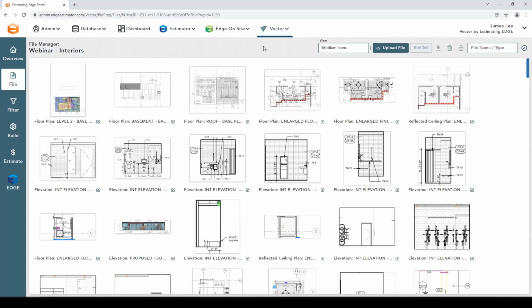So what you're seeing here is a list of all the sheets that the architect has made available to us inside of this Revit file, okay? So these are so much more than just background images. These are the plans that you're accustomed to working with every day, floor plans, ceiling plans, sections, elevations, and details. But besides just the image of the plan, they're also going to contain actual data from the model. The three-dimensional model is going to be broken up into these different sheets, depending on where certain shapes exist, on what floor, what sections or elevations they're a part of.